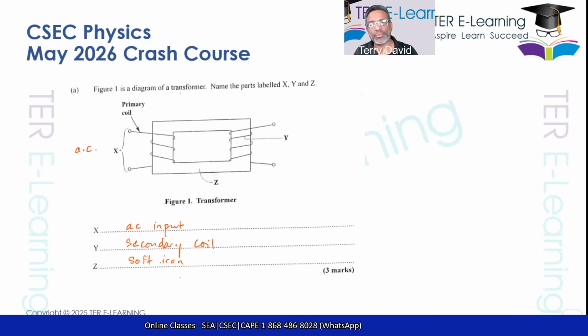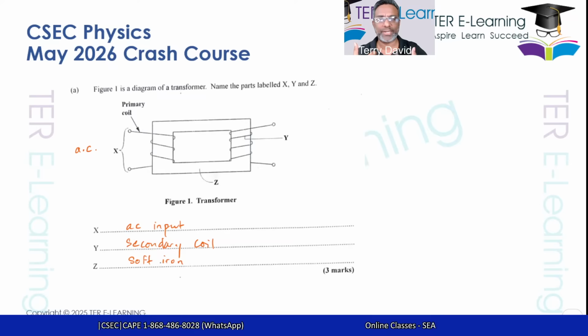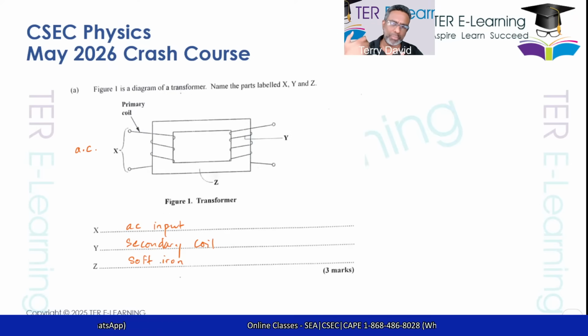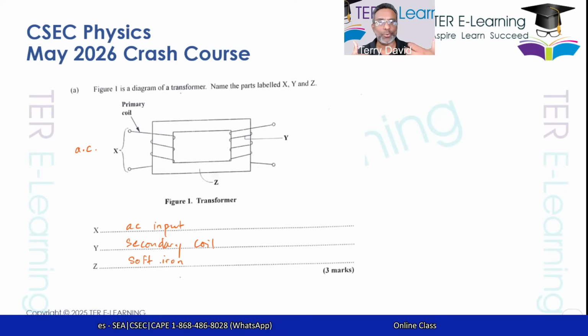With respect to a transformer, that is exactly what's happening here. Your 2 coils, your primary and your secondary coils, they are not physically connected, right? They're not physically connected. But if we have an alternating current flowing in the primary coil, so by the way, you all have to be able to explain how the transformer works. So this is how it works. Alternating current in the primary coil creates an alternating magnetic field. This magnetic field is located in close proximity to the secondary coil.